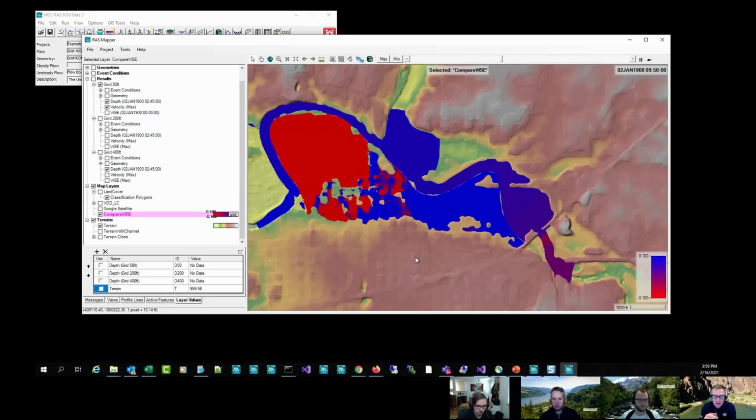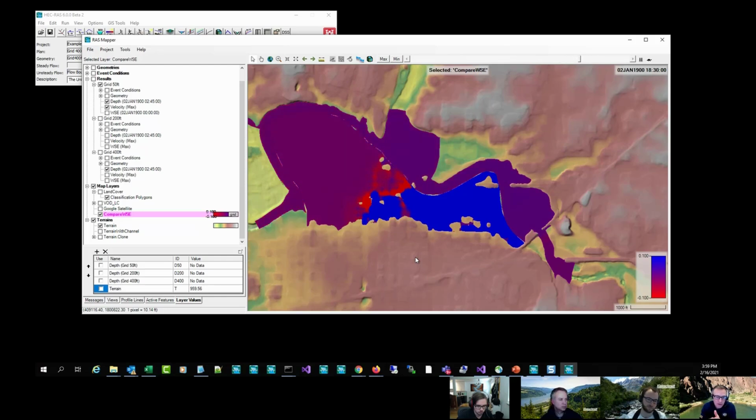There is. Those are the inherent problems that folks should be familiar with, like for max velocity and using max velocity at the same time with max water surface profile. If you're trying to do that, the maps that you're going to create within RAS will handle that okay, because we brute force and figure out when you had the max depth times max velocity. We brute force for every time step when that's appropriate.